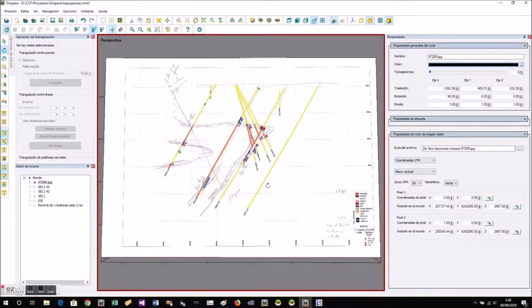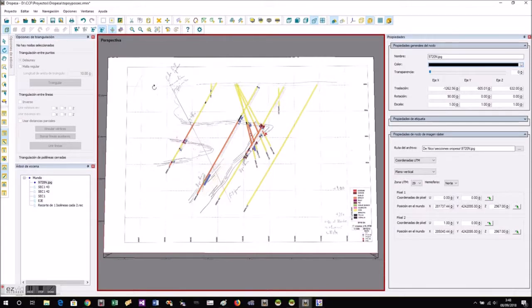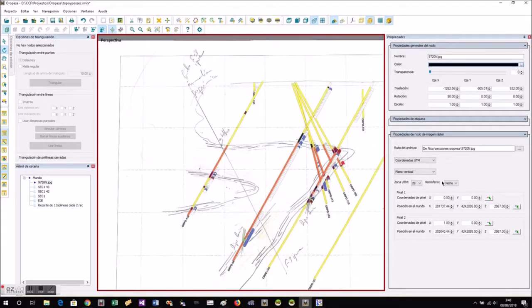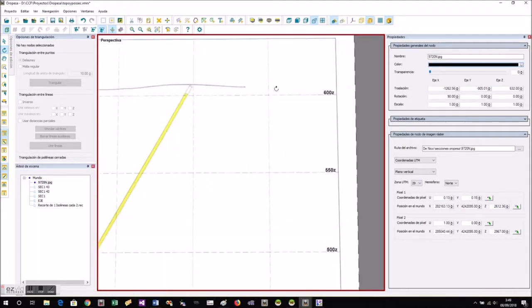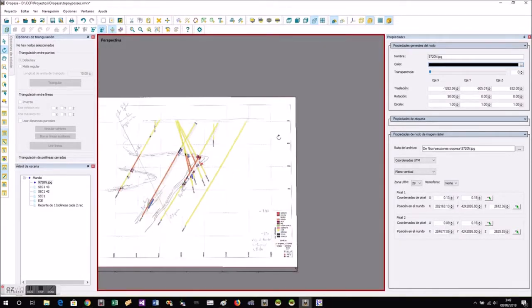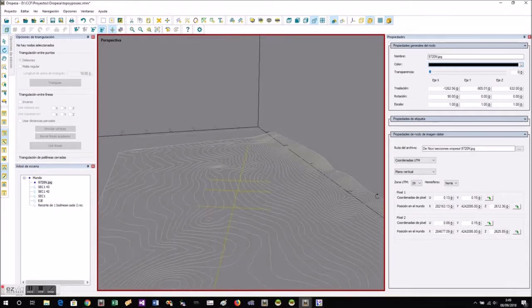Once it's marked like that, it's much easier to place it, right? Let's do the same. Let's mark in the window georeferencing that is about a vertical plane, and as we have commented, it is no longer a plane parallel to xy, nor yz, nor xz. Vertical, we mark the pixels. You can usually mark a pixel and its coordinate. I'm going to mark the pixels first. I frame the 2 pixels first and then the coordinates. So now I give coordinates to one, telling it it's the yellow line on the left, the other on the right.